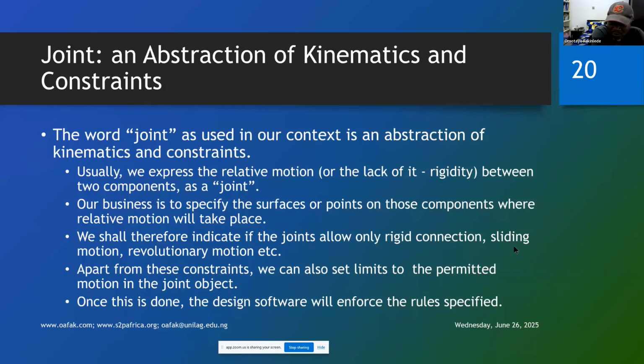You don't have such problems with as-built joints. So one way to avoid that is to design in such a way that the 2 objects are already in their correct locations with each other. In that case, you specify as-built joint and you will not have the problem of anything moving to join anything.